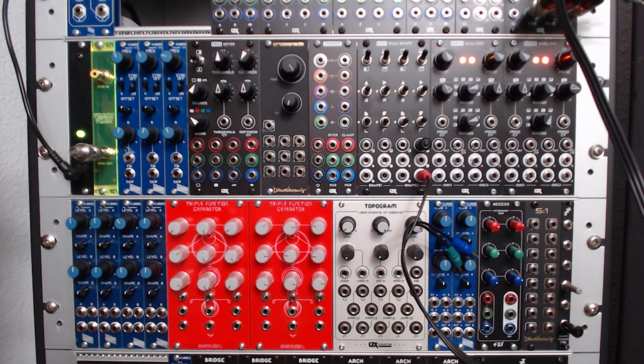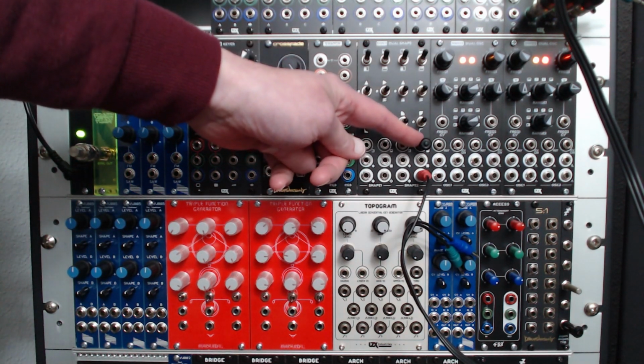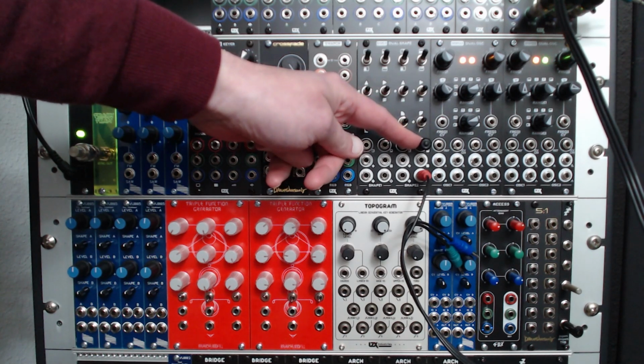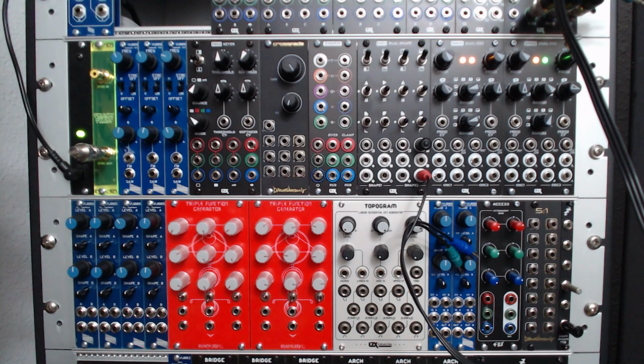And in order to make sure I'm only getting a single ramp, I've inserted a dummy plug into the vertical ramp input. DSG3 has a horizontal and a vertical input. If nothing's plugged into those inputs, we'll get the internal ramps. If we want to get just a single ramp, we can break the normal to one of the other ramps.